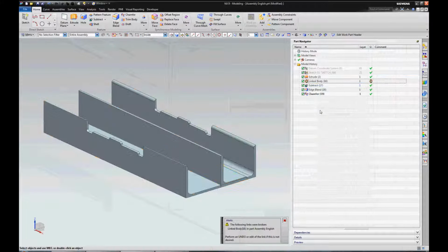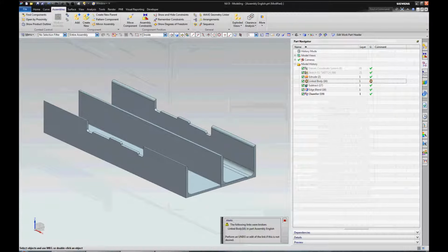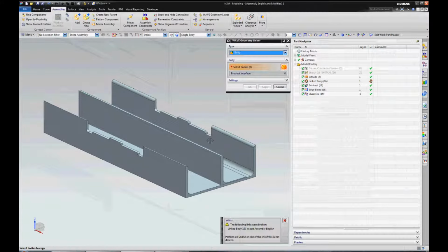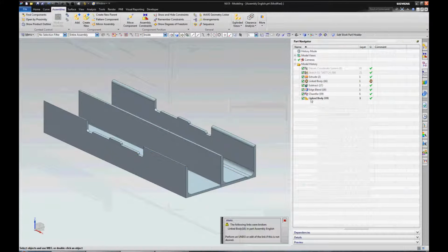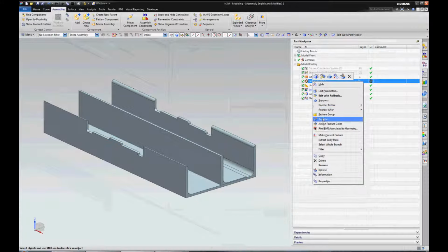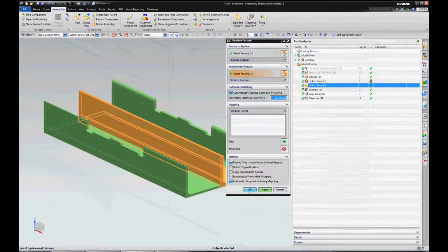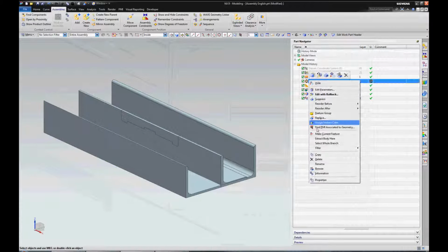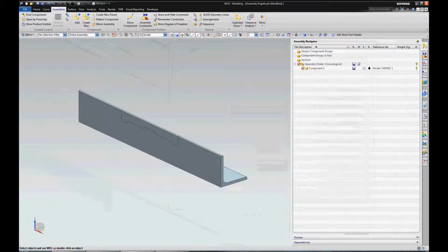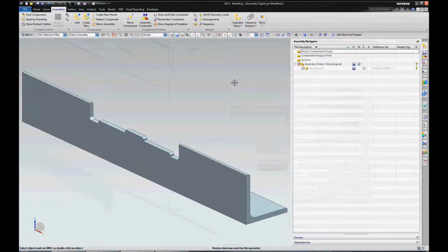The wave copy is now a broken link. We simply need to create a new link and run an automatic feature replace tool. Right click, select replace, pick a new feature and press OK. When we use wave copies of solid bodies, we need to do some weight management, but instead we have more flexibility when we have to replace a component with a new one.